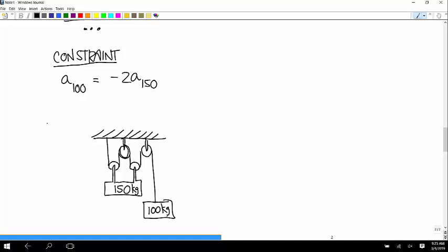You get more effect because when you took the free body diagram of all the hanging stuff, you'd have 1471.5 pounds, the weight of this, and then you'd have 4 cable tensions. And so if it's static, you're just dividing that weight by 4. The more of these vertical cables you have connected to your hanging thing, the more you reduce the weight. At some point, friction catches up with the benefit of adding more pulleys, so there's sort of an optimal number depending on what pulleys you have.